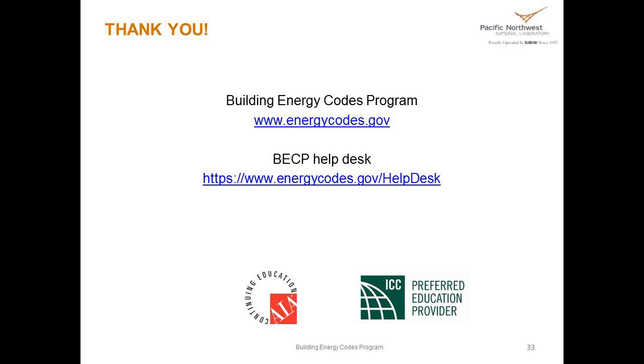That's a good question. So actually, when you have daylighting savings, they come from turning the lights off in the space. What you would see is your cooling load would actually decrease, because the lights are putting out some heat together with the light, and so when you turn the lights off, you have less heat. And so your cooling load goes down, but you do see an increase in the heating load.